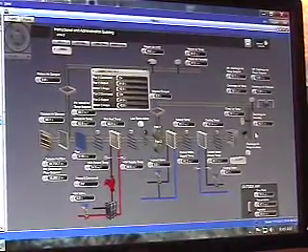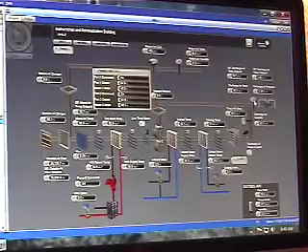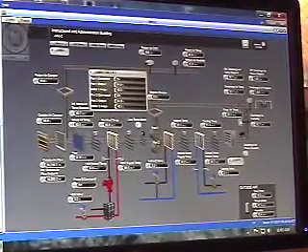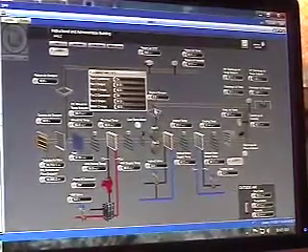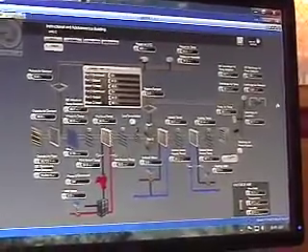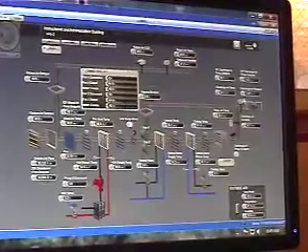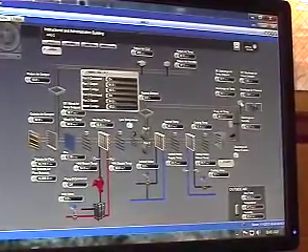Your controlling sensor is right here, after the 2 ducts combine. The reason why we do that is because there's a potential why this is modulating up and down. This is what's going out to the space. This is the sensor that we truly care about and want to maintain its set point.